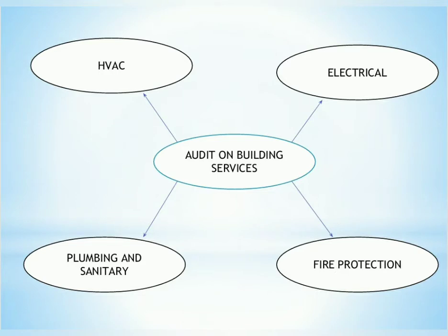Second is electrical. The design, installation and maintenance of electrical systems differ significantly based on the power rating. In the code of practice for electrical installation, 600 volt is considered low voltage and is usually employed in commercial buildings in Malaysia. The usual electrical system components are transformer, wiring, distribution equipment, protective device, lighting, standby emergency power supply, and grounding and lightning protection system.